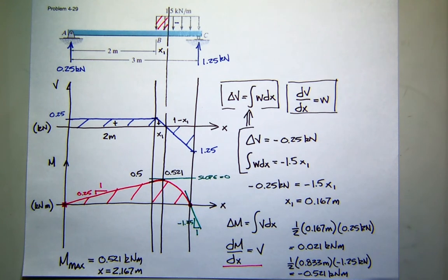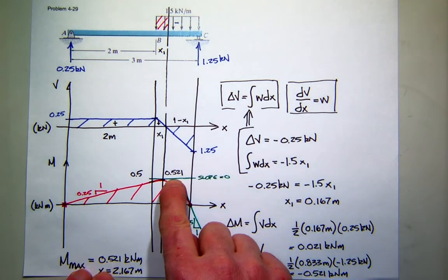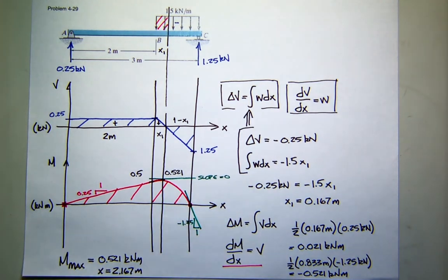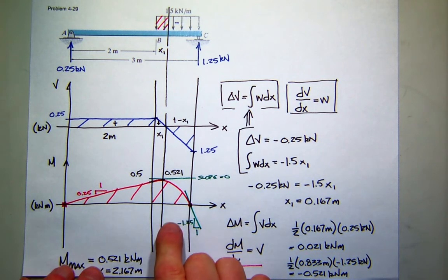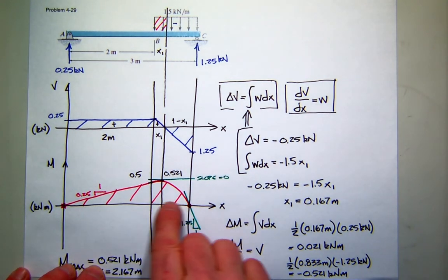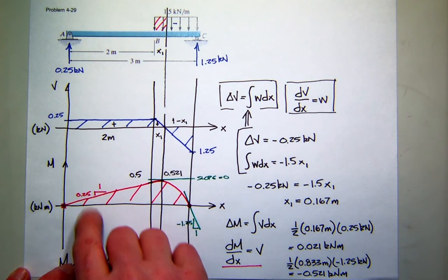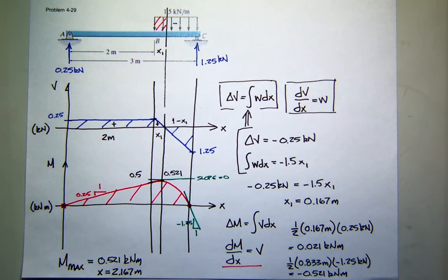But at a minimum, you'll design your beam for the maximum moment. If this is a reinforced concrete structure, it might give you some ability to reduce your reinforcement. Over here where the moment gets low, you may not need all your reinforcement. So you could do what's called bar cutoff. And you'll need the moment diagram and the values in order to know where you can cut your bars. So our course isn't very exciting because we don't ever actually get to do any design, but our work is the fundamental. That's the basic things you need in order to do the next part.